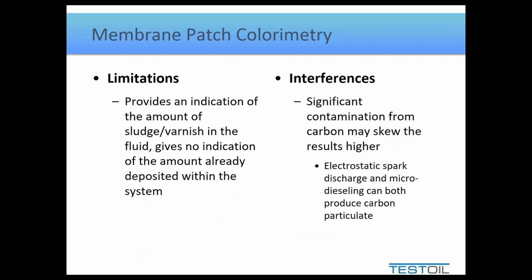So to understand this, the limitation of this test is it only tells us how much of these insolubles, which eventually as they deposit we would call sludge, varnish, lacquer, tar. It only tells us how much is able to be trapped on the patch, which means it's how much is in the fluid. So it doesn't really tell us how much has already settled out within the system. So we have to appreciate that right away. It's that constant joke I make with people about what any laboratory test can tell you is what's in the bottle. It doesn't necessarily tell you what's in your system, because if it's stuck in your system, well, you certainly didn't put it in the bottle when you sent it to the lab. So this test only tells us how much of the insolubles are in the oil.